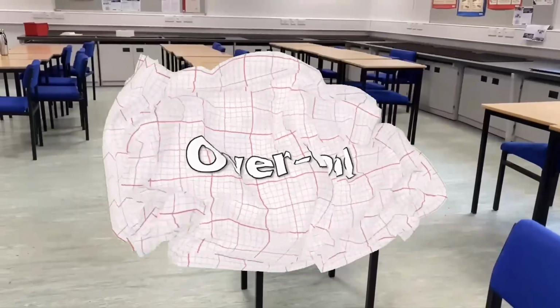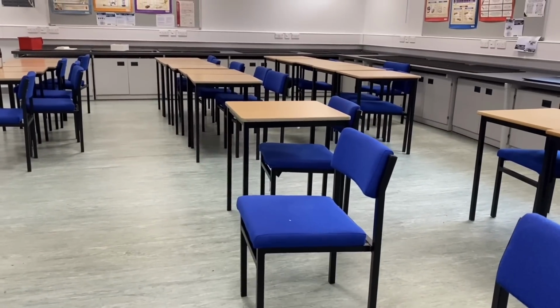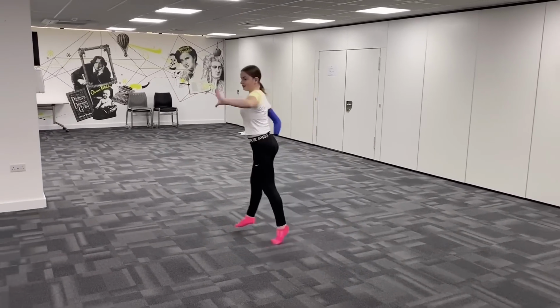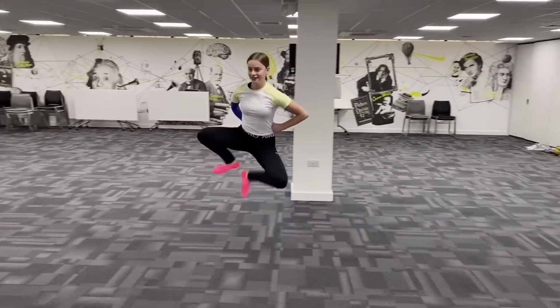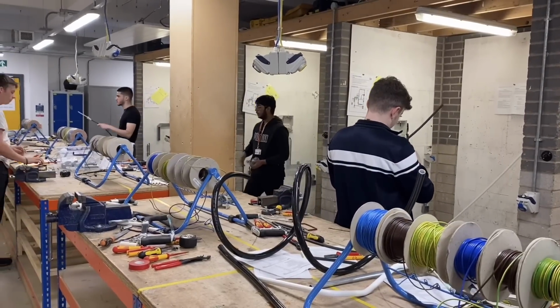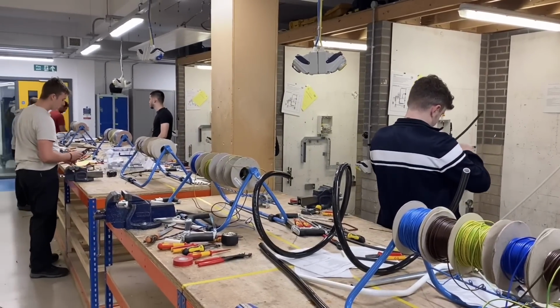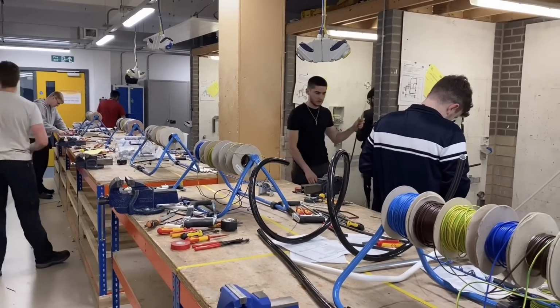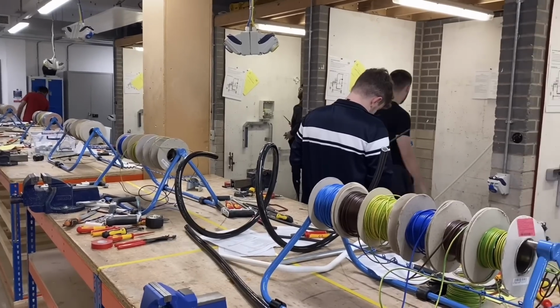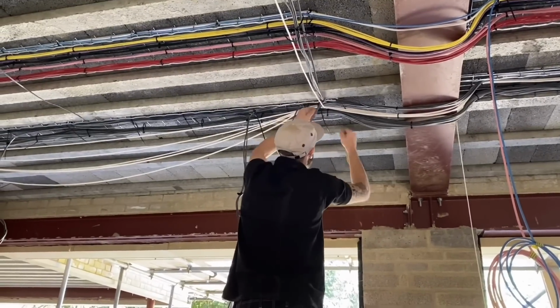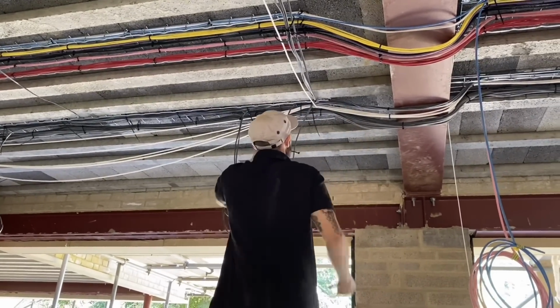Now, for many circuits, this type of fault is not actually a risk. Take a lighting circuit in an office, a classroom, or a workshop, for example. The designer will have looked at the specific lights being installed, calculated the current that will flow when they're all turned on, and selected the appropriate cable and protective device. As all the lights are fixed and might reasonably be expected to be in use at the same time, this type of circuit is never likely to get overloaded. It might happen if someone came along and extended the circuit without doing the proper calculations, but then it strayed away from the original design.